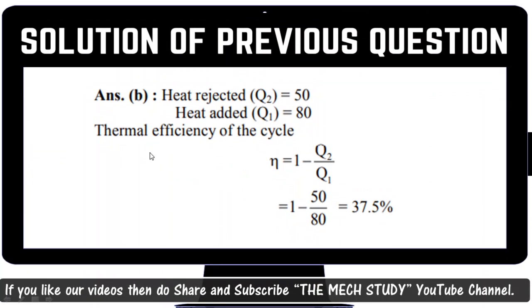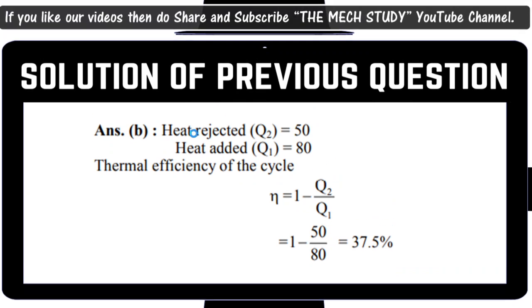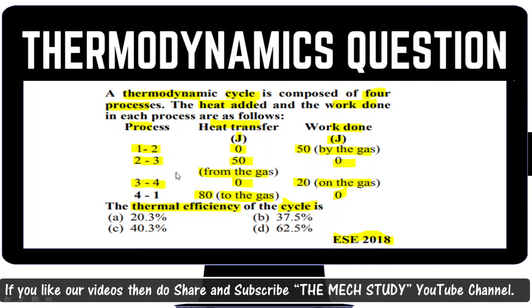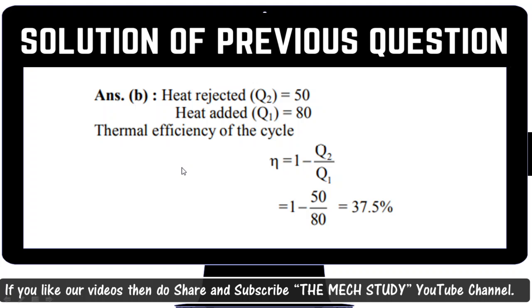Thermal efficiency is 1 minus Q2 by Q1, and also 1 minus T2 by T1, which is the theoretical efficiency. But whenever the heat rejected and heat added are given, you can go with this formula. Once you put in the values of Q2 and Q1, you will get 37.5% thermal efficiency of that particular cycle. I hope this question is clear now.